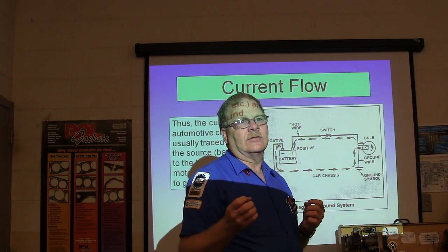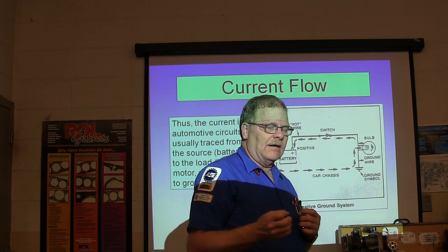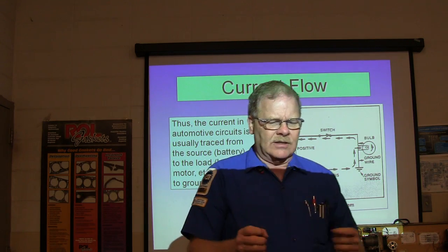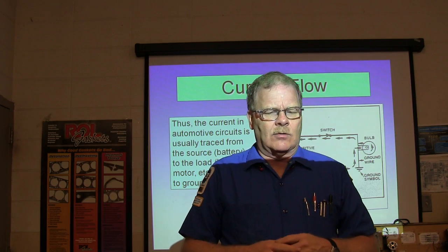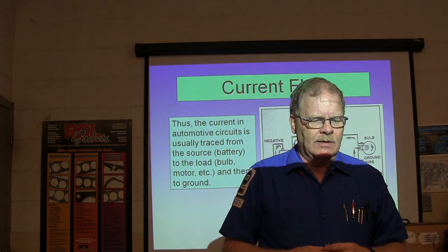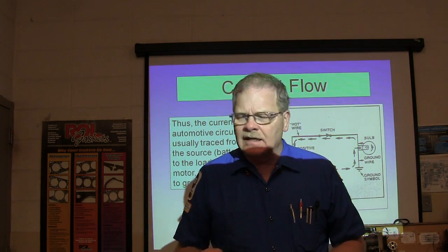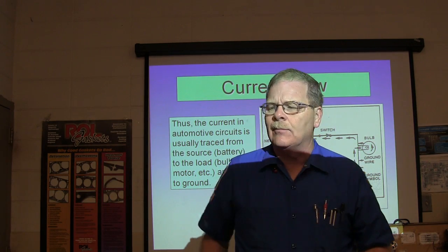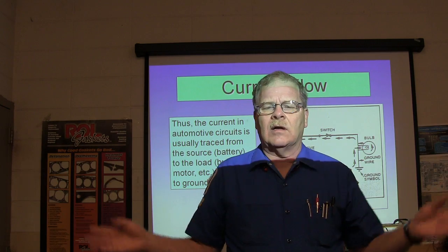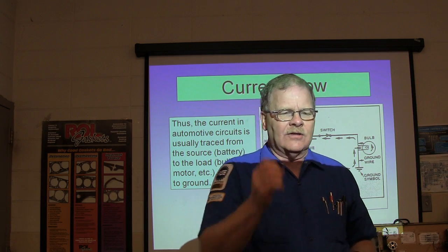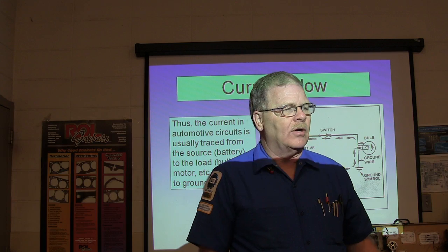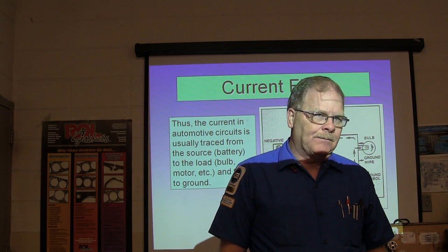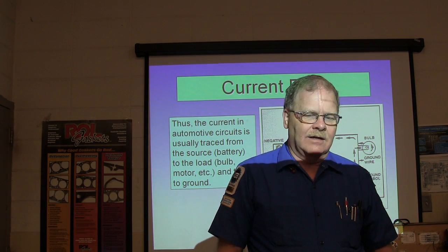I mean, a lot of the instructors don't like test lights, but I got in a mess one time using a meter to check the anti-lock brake system on a Taurus when I was working at the dealership, and I was going by the book and it said get a meter and see if you've got more than 11 volts here. So I checked it and I had more than 11 volts. And I went all the way around Robin Hood's barn. Then I found out this more than 11 volts I had here wouldn't burn a test light. A meter will lead you astray if you're measuring something.